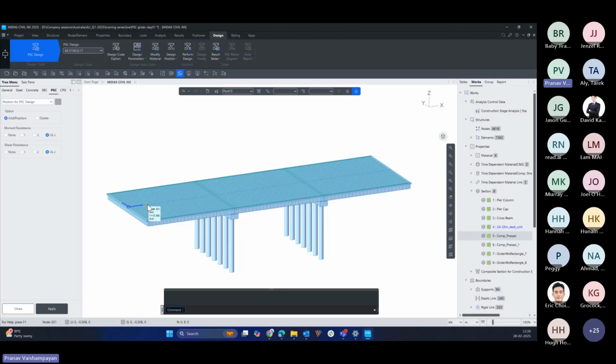We have identified 1813 is the maximum load for moving load. So we are going to select the same span where 1813 is included. In here you can type 1803 to 1827 and press enter. It will select all the elements between 1802 and 1827. So total 26 elements are selected. If you hover your mouse over this bar, you can see the number of selected elements is 26.